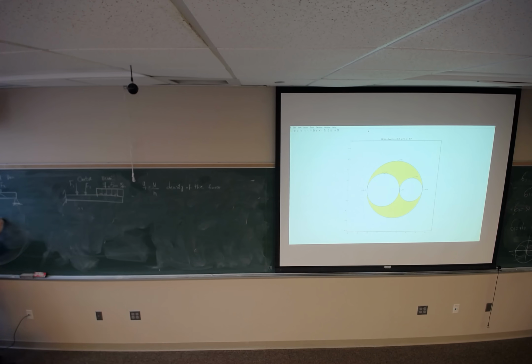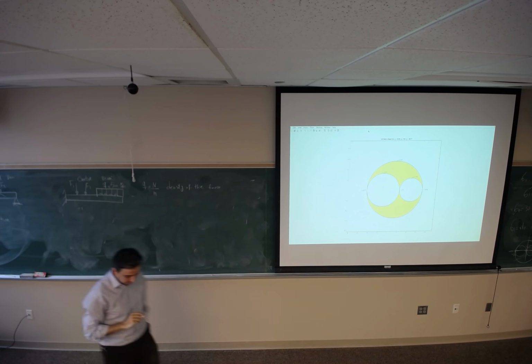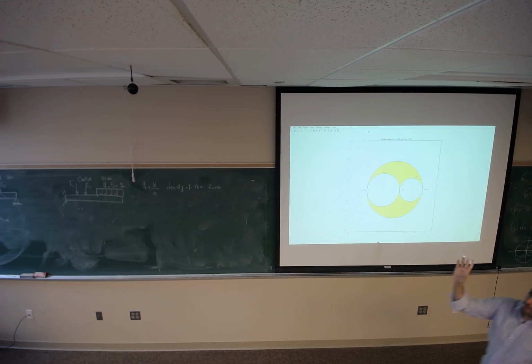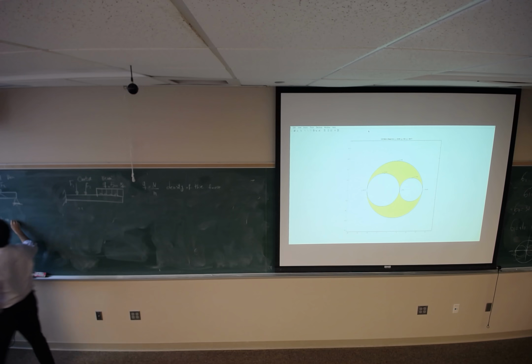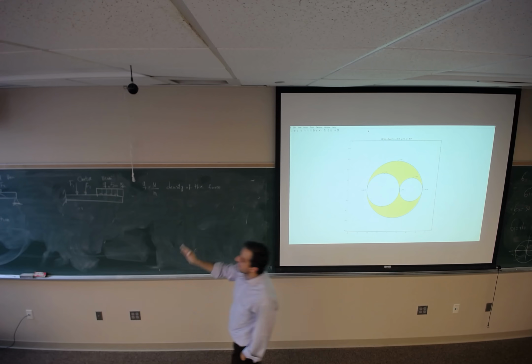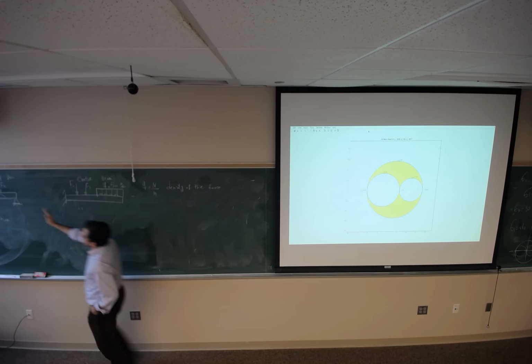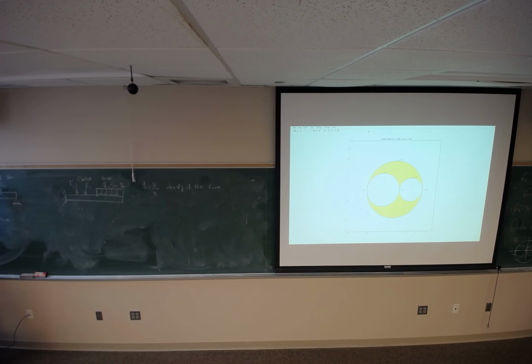If you remember, the first thing that we defined in this course was critical section. This is the first mechanical component that we start working on, and we would like to find the critical section for a given beam with the load applied to that. So what do I mean? I would like to find at which section, at which location of this beam, I will see the largest amount of the load. Or if the failure occurs, at which section is it going to happen? This is the definition of the critical section.